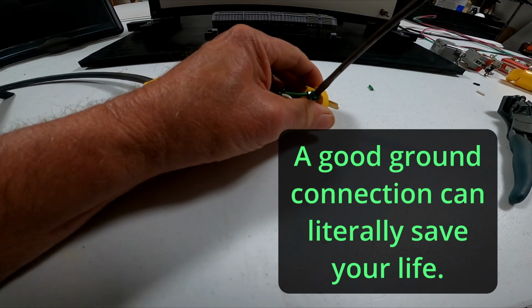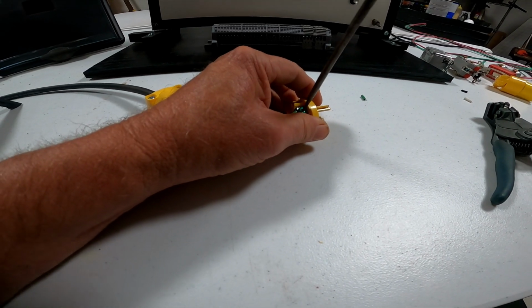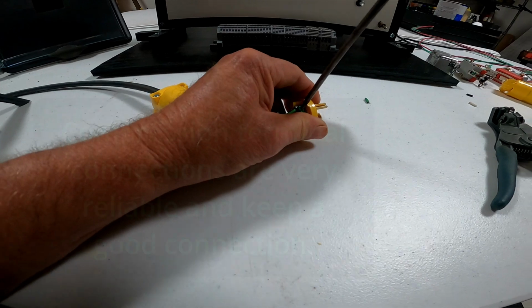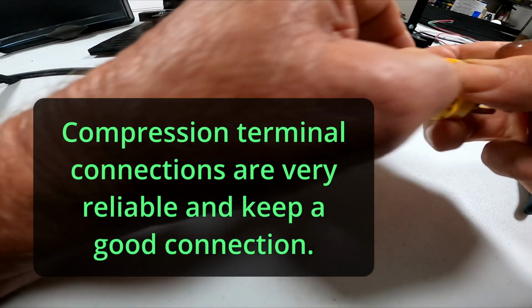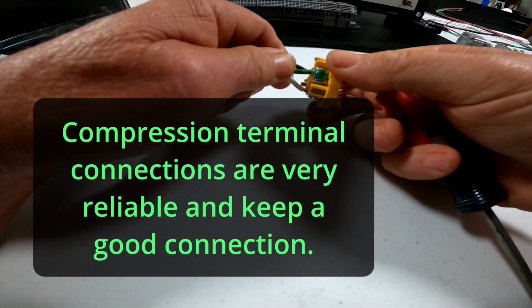And these are compression fittings, by the way, which are my favorite. If I've got to have something, I would prefer it be a compression terminal. Now, give everything a good tug and make sure it's good and tight. One final inspection to make sure there's nothing loose.